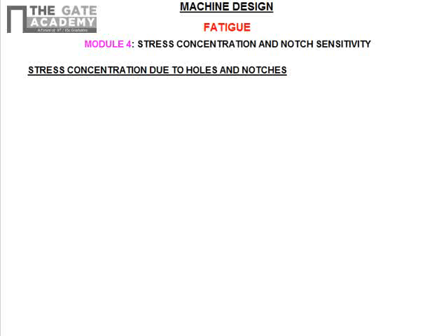So now we have seen how to apply the stress concentration factor for static loading for ductile and brittle materials. Now we have seen that the stress concentration factor Kt depends only on geometry. So how do we determine the stress concentration factor? We will see some common geometries.